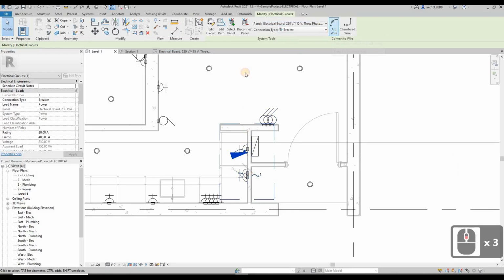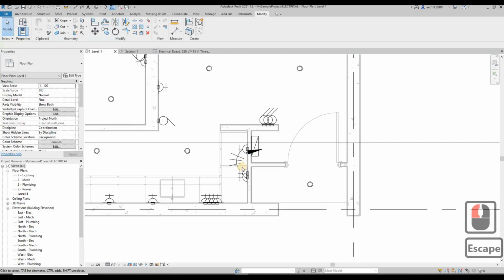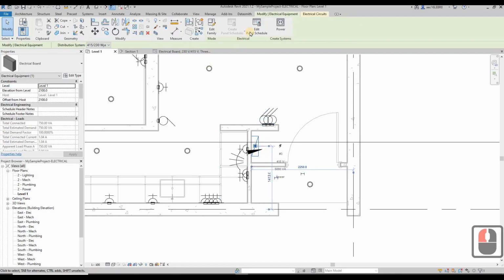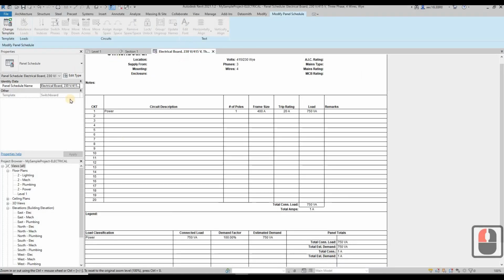You can click on this arc wire to show this wire connection. So this 3 power socket is connected to this electrical distribution board. How are we going to justify this? We can click on this panel board and then click on edit panel schedule again, or you open this electrical DB again. Then you will know that this power is already connected to this electrical distribution board. So that's how easy it can be done.